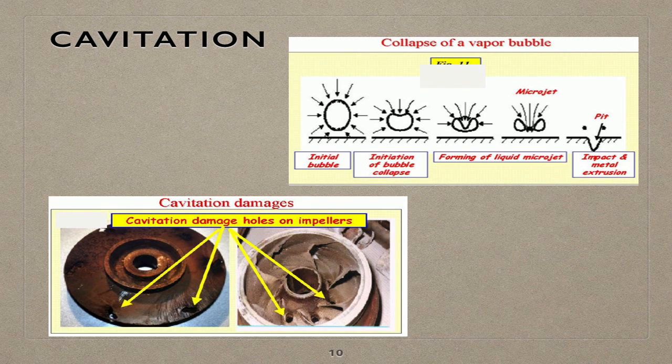In order to prevent cavitation, we should consider how to select an NPSH, net positive suction head required. When liquid is pulled into a pump, the flow into the suction causes a slight drop in pressure before pressure is increased through pumping. This pressure drop is related to the pump design and flow rate, and is called NPSHR.